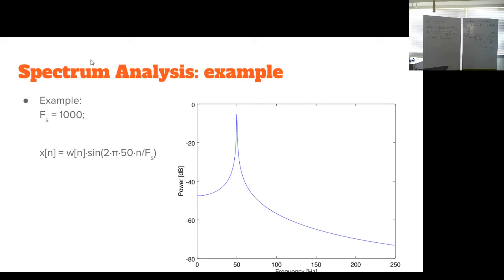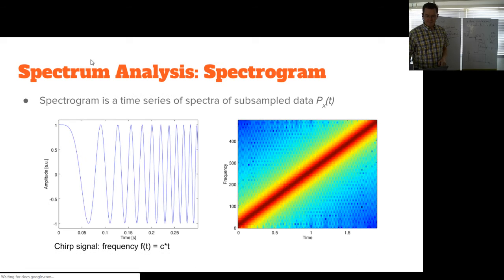Okay, but it does not look exactly periodic since it has these funny envelopes, because digital signals are never exactly periodic. One is the sampling rate does not match this frequency exactly, and another one is when you do a digital sample and calculate something, it's always within some limited time, meaning that you are always multiplying your signal with a box, and that gives you some effect on the frequency response or spectrum. Aha.